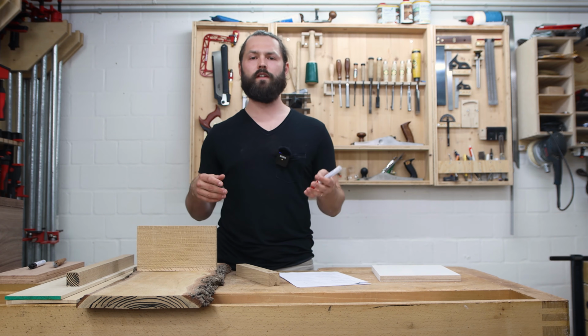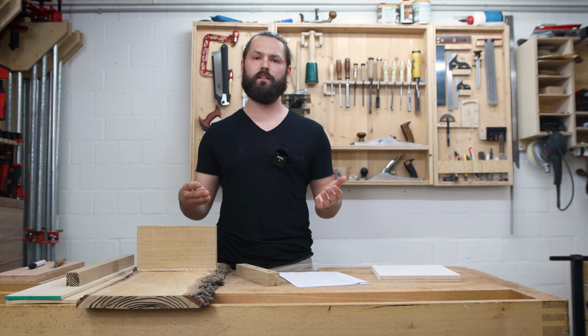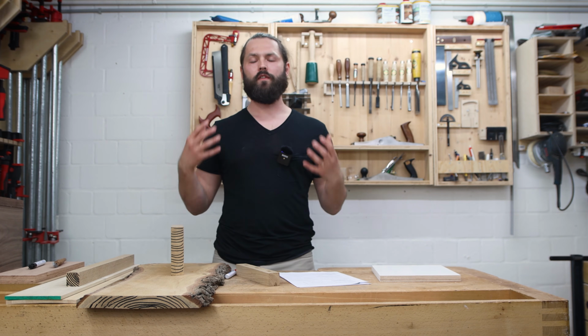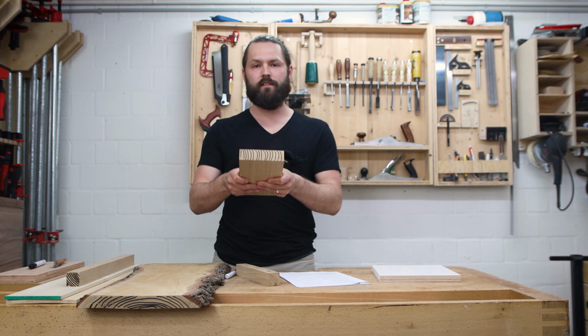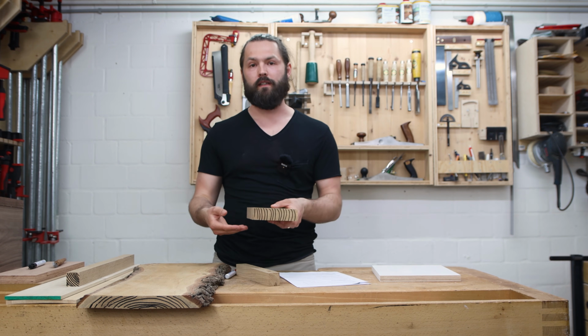I will link you a few of these wood movement calculators down in the description. There are basic construction methods that have been used for the last hundreds of years to account for wood movement in a solid wood furniture project. Now the 3 biggest factors for wood movement in your project are how dry the wood you buy is, where your furniture will live, and where you build it.